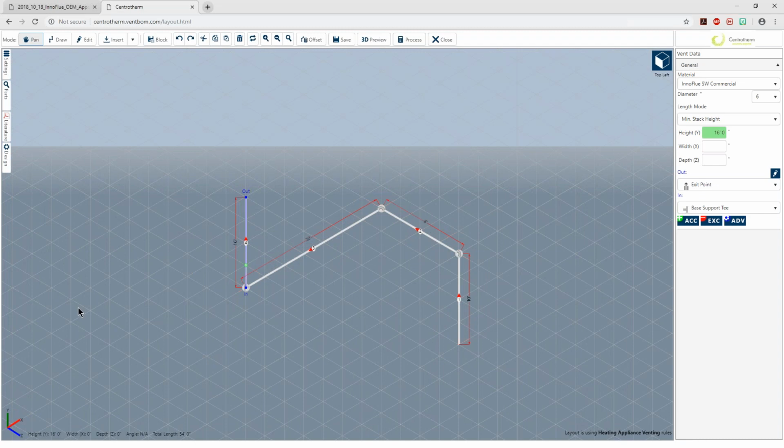Base support offers additional vertical support. So 16 feet isn't a whole lot. This pipe doesn't weigh a whole lot. The system always puts it on there. We always recommend it. If this had been shorter, like 5 feet, you absolutely do not need a base support. You can use just a standard 90. So that's a good question. I wouldn't say it's interchangeable, but certainly an elbow will work in certain vertical runs if supported properly.